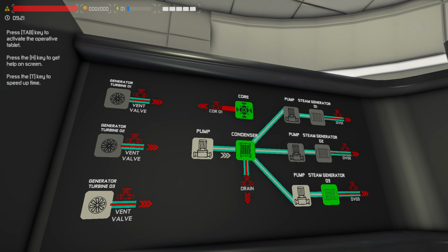You could have convection, which is based on currents. Like in your convection oven, the coils heat up, which creates a mini current where hot air rises and the colder air goes down. You can imagine that circulating. Well, that's what the reactor coolant pumps do. They circulate water, so it's forced convection.